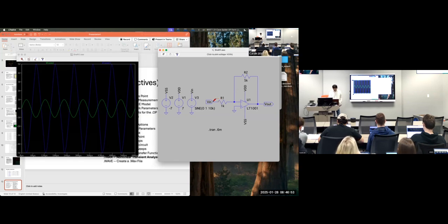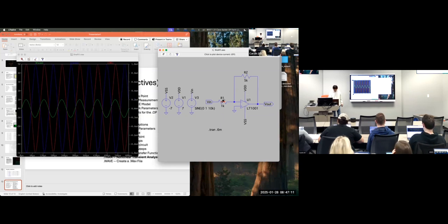But voltage is not the only thing we see. If we hover over a component, let's see, like a resistor, we're given a weird icon. This is a current ammeter, there you go. A little circle with the arrow running through it. Click on that. That can show us the current running through a component. So, like I said, if you are in lab and you want to find out values, if you don't want to do the analytical method, you can just whip it up on Spice and see what values show. It gives you a good starting point or a nice guess check.